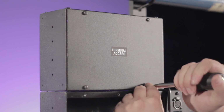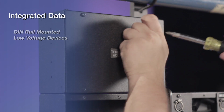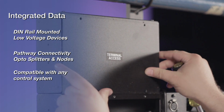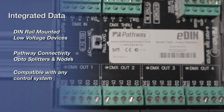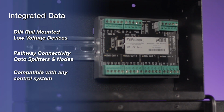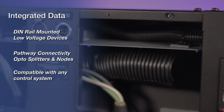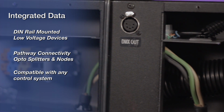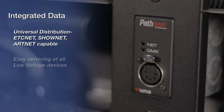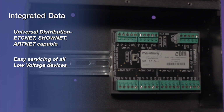In Altman 450 connector strips, the cabling in the low-voltage barrier originates from a DIN rail mounted control box. This control box allows for integration of Pathway Connectivity DMX 512, RDM optosplitters, Ethernet nodes, and other DIN rail mounted control devices. The use of Pathway Connectivity devices ensures cross-compatibility with existing and future control protocols and provides the designer, contractor, and end user with a universal distribution system. The DIN rail allows for easy servicing of all low-voltage devices.